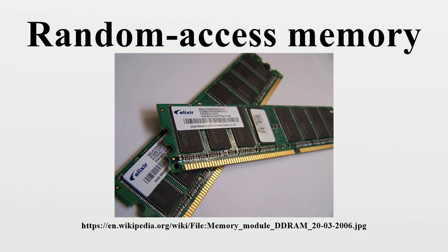Today, random access memory takes the form of integrated circuits. RAM is normally associated with volatile types of memory, where stored information is lost if power is removed. Although many efforts have been made to develop non-volatile RAM chips, other types of non-volatile memory exist that allow random access for read operations, but either do not allow write operations or have limitations on them. These include most types of ROM and a type of flash memory called NOR flash.